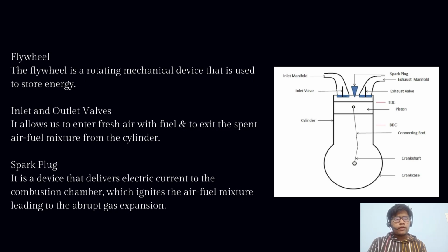There are two kinds of valves, inlet valves and outlet valves. To control the inlet and exhaust of the IC engine, valves are used. The number of valves in an engine depends on the number of cylinders. Two valves are used for each cylinder, one for inlet of air fuel mixture inside the cylinder and the other for